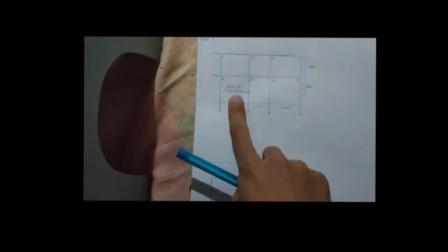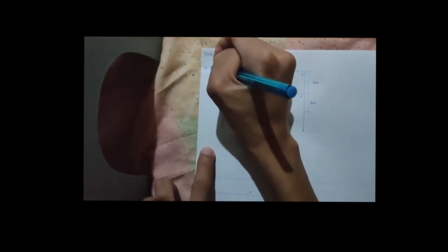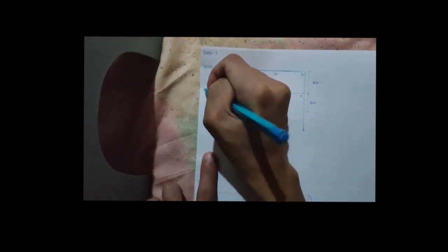This one here. So in our second step, we'll get the actual force in the column of the first story. This one here, and we have a point of contraflexure. So the first thing we will do here is take moments about the point of contraflexure. So, I forgot, you have 8 kilonewton and then 10 here.